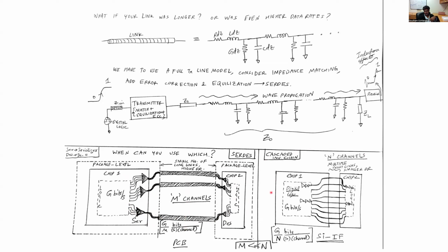However, if we consider case 2, which will be described later in the course, called the silicon interconnect fabric, which is an advanced packaging technique wherein we no longer have the PCB, the package, and the laminate, but rather the chip in die form is directly attached to some interconnect fabric where the interconnects can be made using back end of line processing at very fine interconnect pitches.